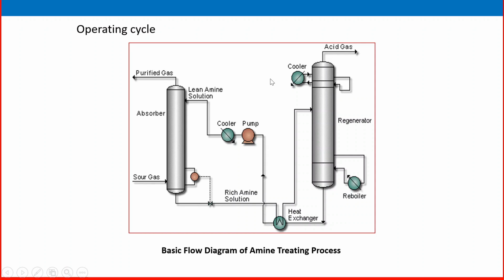That is cooled back, and some portion of it re-enters here. That way, the gases are released, and pure amine solution without H2S settles at the bottom of the tower and slowly overflows to the next section, the surge drum, which I will explain in detail.